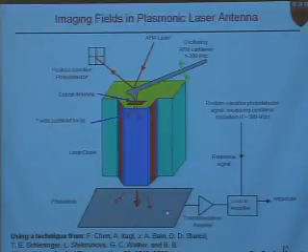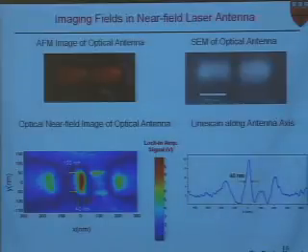We take that through a transimpedance amplifier, and then to a lock-in amplifier, and the reference signal to the lock-in amplifier is the signal from the position-sensitive photodetector that monitors the oscillation of the cantilever, because the cantilever is oscillating in tapping mode at about 300 kilohertz. And this allows us, using this lock-in amplifier, to pull from this photodiode signal the component that's due to scattering by the end of the tip. Because the tip is basically modulating that scattered light at 300 kilohertz. And that lock-in amplifier is somewhat similar to a bandpass filter operating at that 300 kilohertz oscillation frequency. And these are the results that we got.